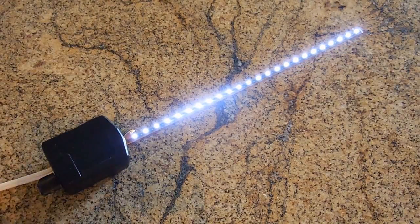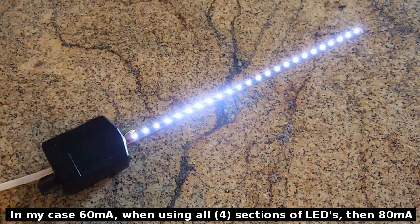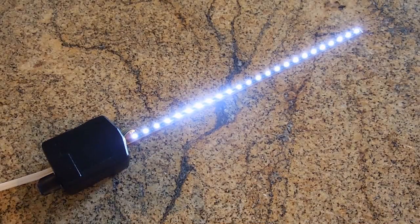All right. And the reason why we're able to use a potentiometer on the output to the LED strip is only because around 60 milliamps is going to be flowing into this strip. So the current level is very, very low. It's not enough to burn up the potentiometer as long as you're using a 0.5 watt to a 1 watt 5K potentiometer like I'm using right here.